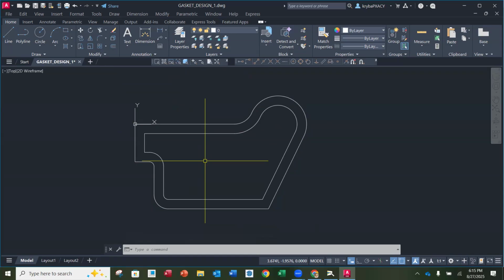Now you'll end up with truly the same thing in the end, but there's another reason why we would want to use the polyline. If we know, for instance, that we're going to be sending this to a laser cutter and it's going to be using the path of the geometry that I created, if I don't have everything properly joined at the corners or I have overlaps, the polyline command is going to give me an error. It's going to say, I can't do this. That's a really good check, if you want to use it later on for a profile, that the geometry is solid. Does that make sense to everybody?